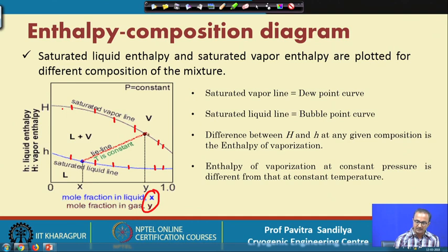That means, when I am reading this, we shall be having the y, the vapor composition, and H, here capital H, represents the saturated vapor enthalpy. Corresponding to this y we have another liquid phase composition that is in equilibrium, and this can be obtained from the XY diagram which we learnt earlier, and corresponding to this point we shall be having another enthalpy. This is the x versus H.